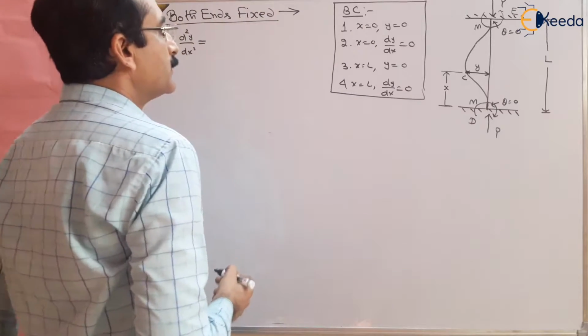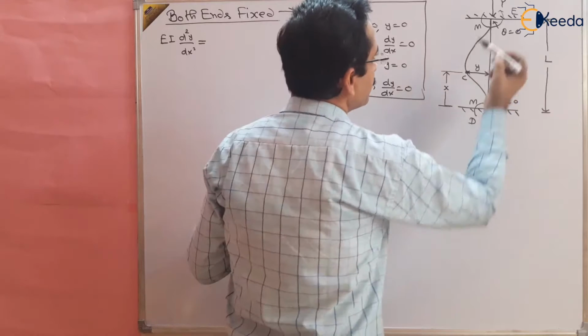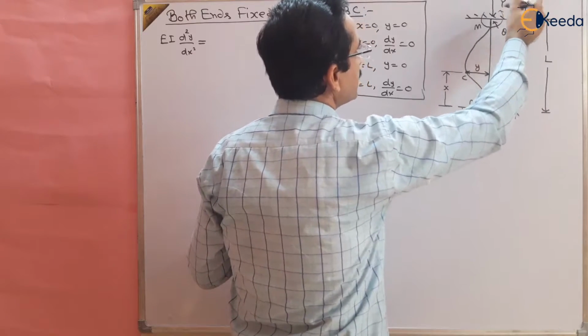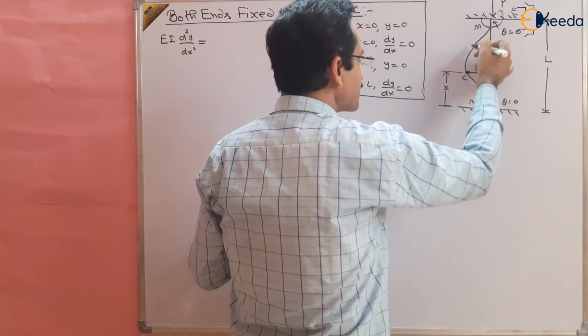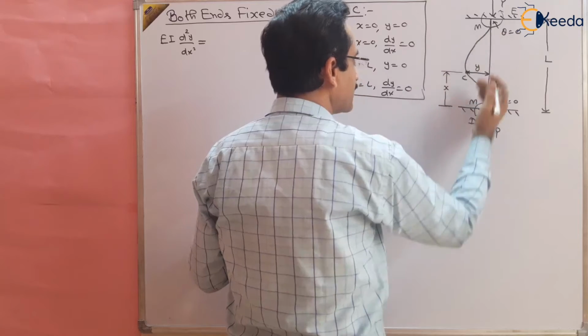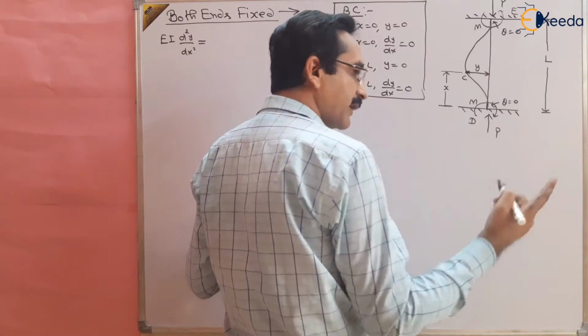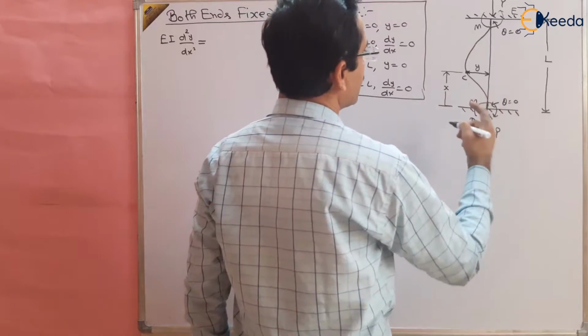So to find the deflection equation, consider the moment due to this load P and this moment M. You know that this is concave towards the initial central axis. About the central axis this is a concave curve, and for concave curves this is a negative bending moment at this point according to our sign convention, right?